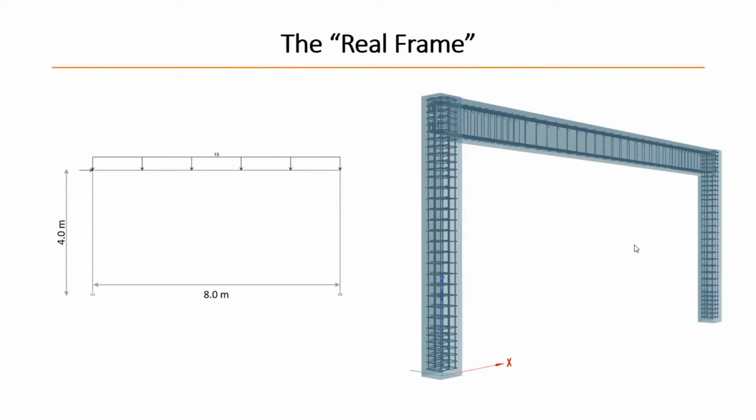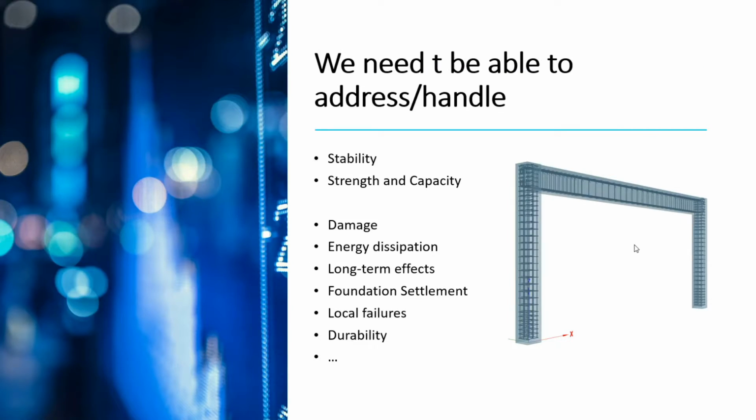Let's go one step forward to the next stage and see what we really need to do to handle the complete response. We need to handle the stability of the structure, first of all. We need to make sure that the structure does not fall, does not slide, does not overturn, and does not have a large deformation.